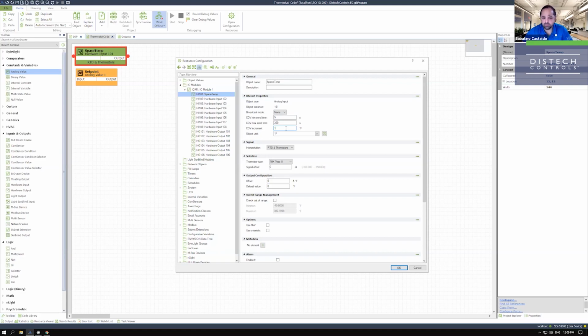If there's multiple changes, for example, a morning warm up scenario where you'll have a lot of space temperature sensors start to change values very, very often or very quickly, you want to throttle that down with something like 5 seconds, 10 seconds, 15 seconds on min send time, or a higher COV increment. So you get to decide which granularity you want to work with.